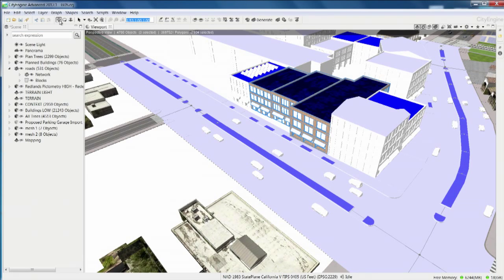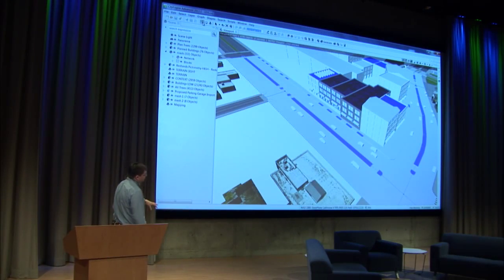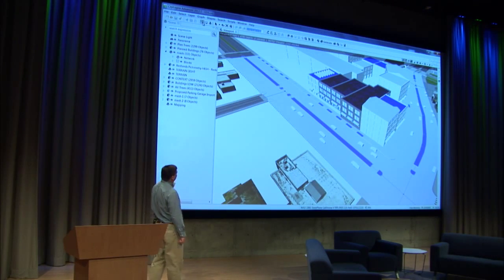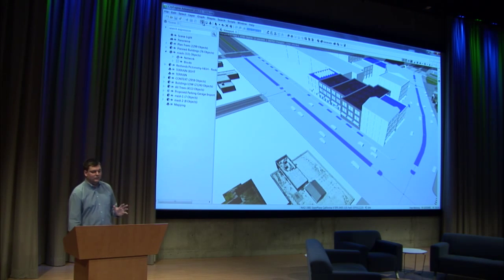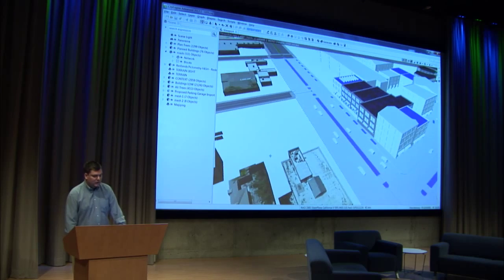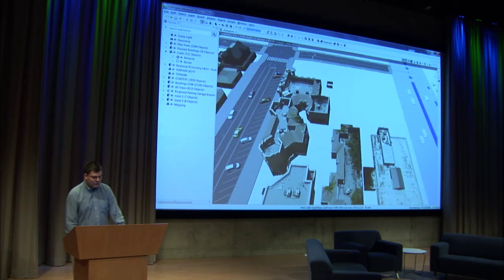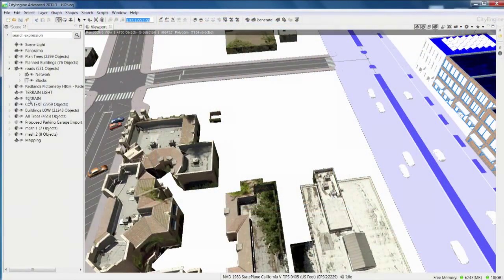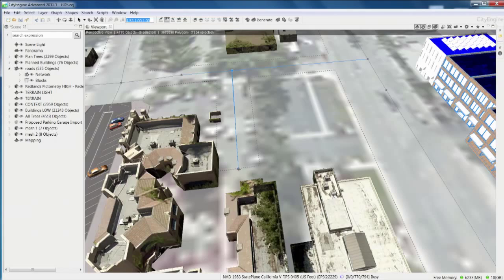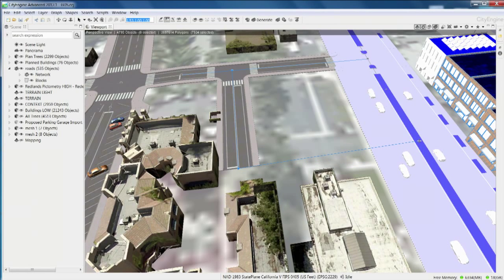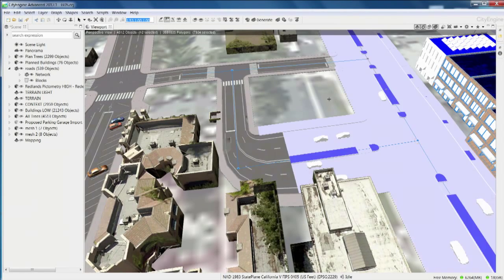Now what I've shown here is creating from street center lines, creating buildings from footprints, creating buildings from parcels, but this is actually also an interactive creation tool. So we can go in and create new features. So what I'm going to do is go ahead and create a new block. We have this kind of empty area here. I'm going to go in and start creating a street. It grabs the attributes from the first street, and then it's going to grab the attributes from the second street, which is going to be a little wide here. So now it generated new streets.